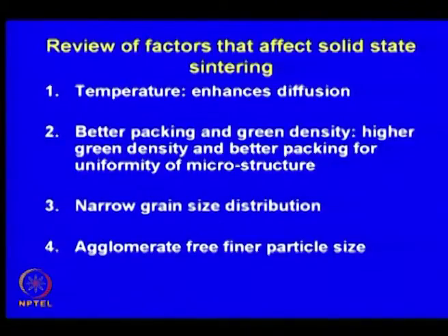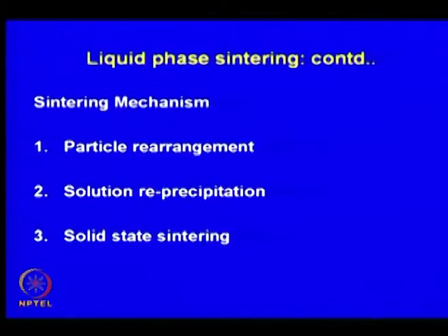The factors that really have to be considered over here is during the liquid phase sintering, the liquid phase which would have otherwise formed an amorphous phase might require to be engineered to form a crystalline phase, so that the mechanical properties, the creep resistance, the electrical properties are within the limits of what we need.